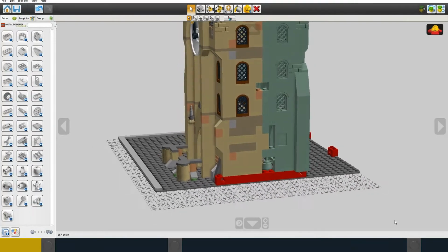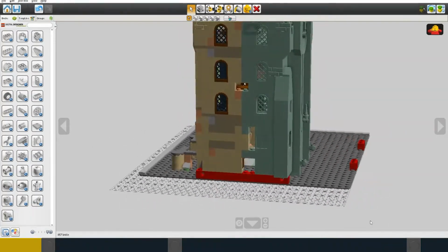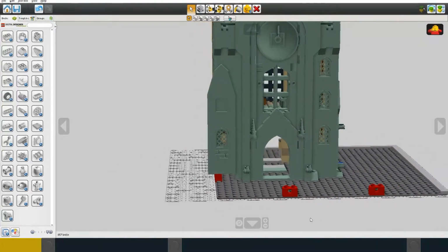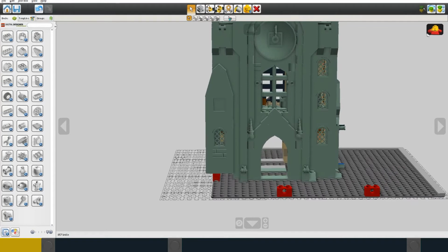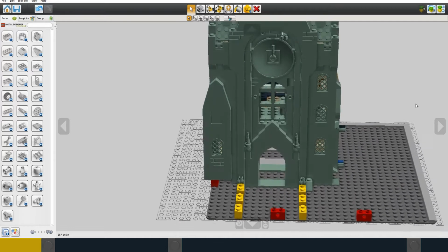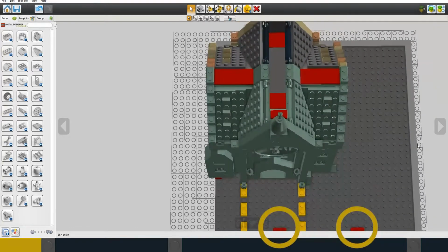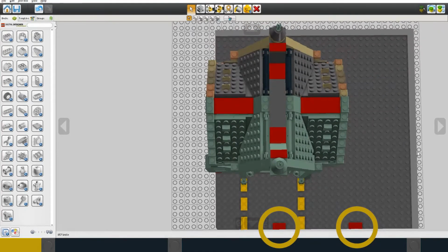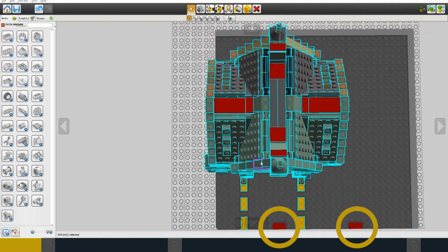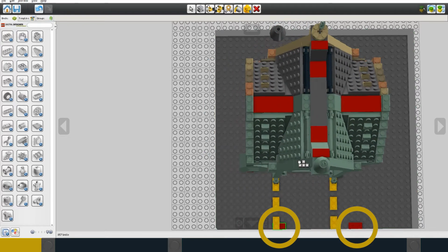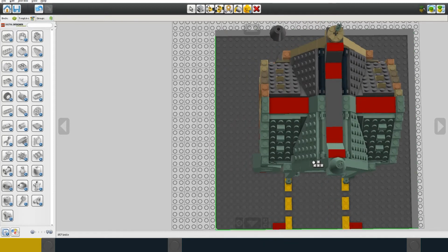Also, if I look at the footprint of a building that is back to back, it doesn't fit in the right place at the back to fit with the modular building standards. Really, I need to shift the centre line of the roof so that it lines up with the modular connectors at the back here. That might be possible, but it gives me an L-shaped building and the front gable would be moved quite a long way over, so it doesn't really give me much room for adding a tower on the side.